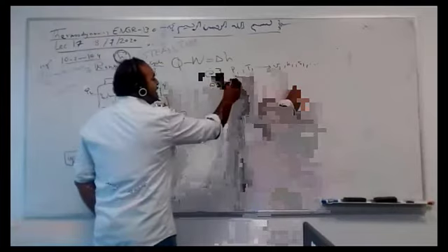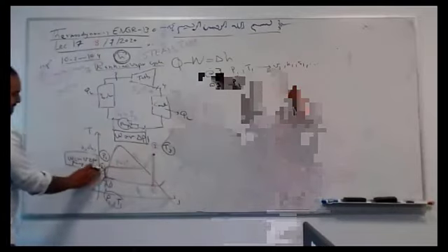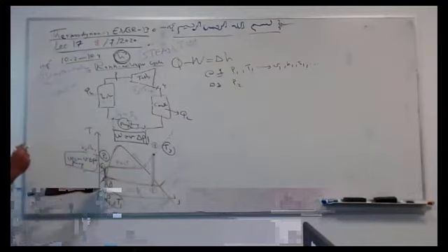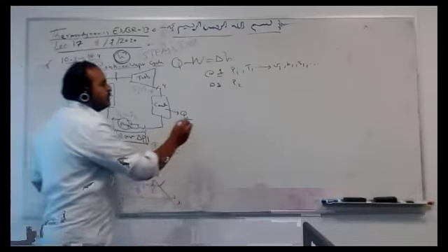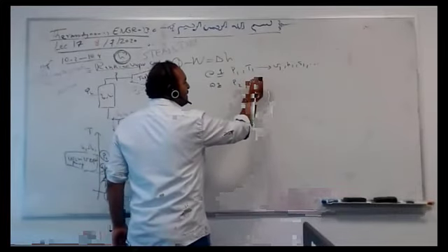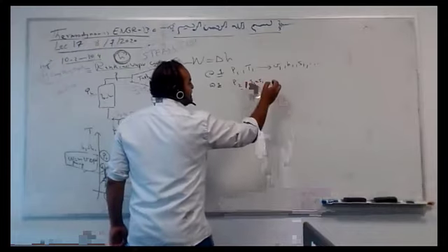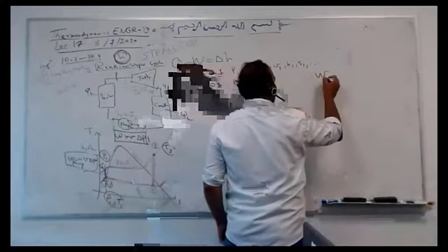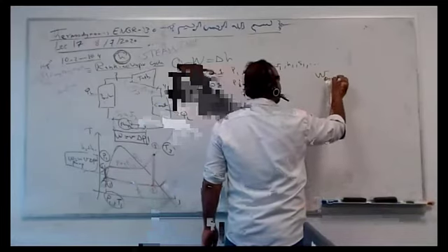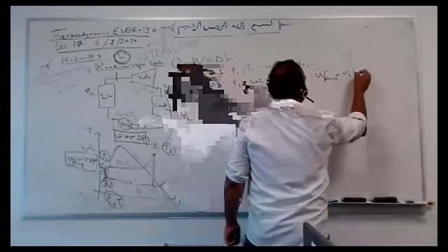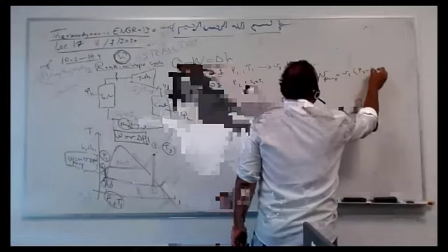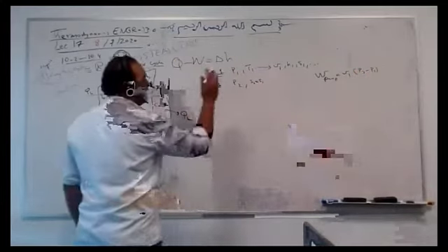At step 2, you have P2. Of course, I give you the pressure ratio, for example, so I give you P2. And you have constant entropy and almost constant volume. So you can say S2 equals S1. And you don't even need this. The work done directly in the pump equals just V1, which is constant, times dP, P2 minus P1. That's it. You don't even need anything at 2.